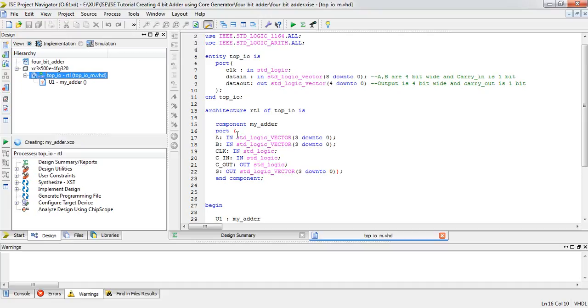If you are doing this core generation feature the first time, then it might take some time, because the first time it will call every repository IP, and it will call the IP from its local directory to your project folder. It is running, so let's wait some time.